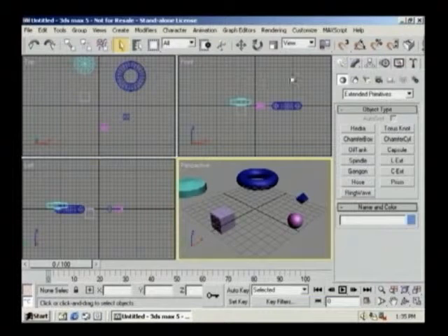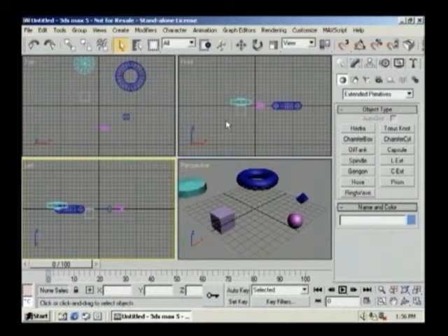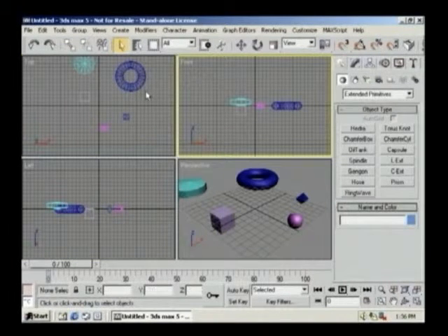The grid that is flat to you is one axis home grid, and the dark lines that cross within this grid, these are the other two. So depending upon which viewport is active and which viewport you are working in, this determines what axis home grid you are creating your objects and your shapes on.